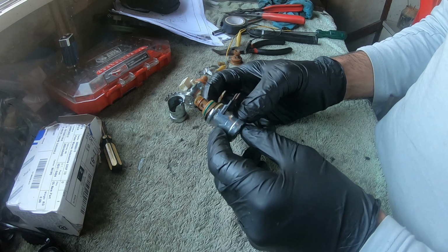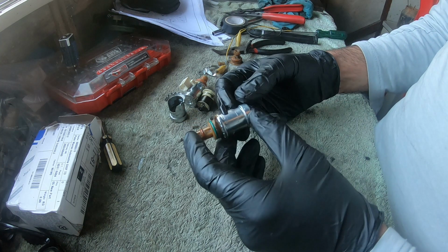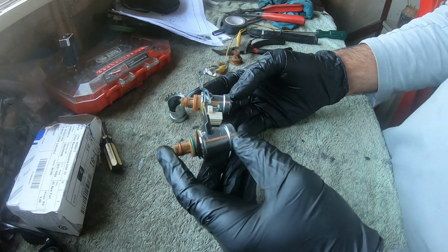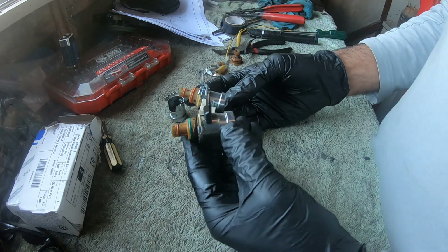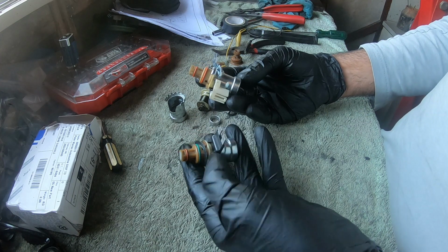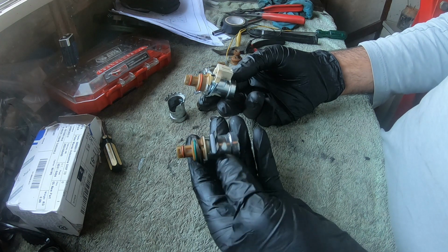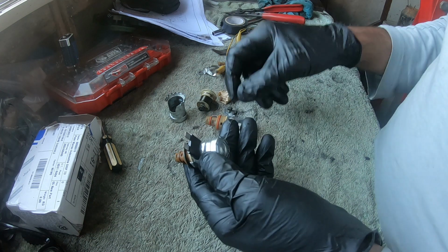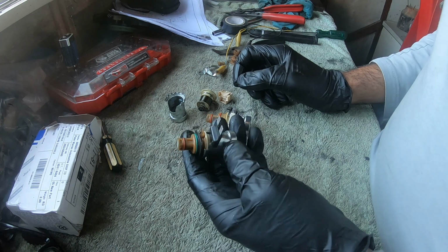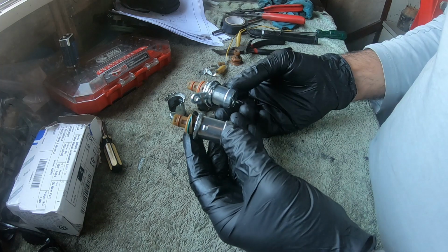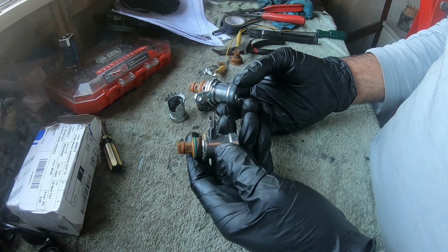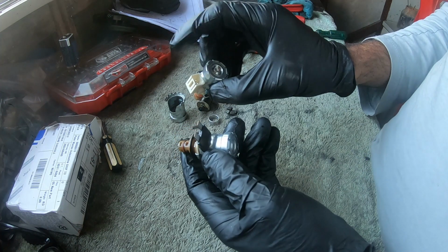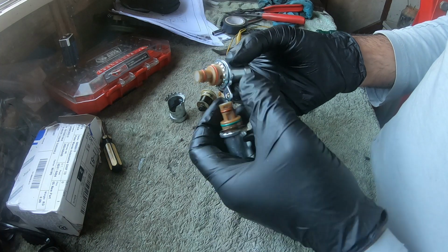In the meanwhile, I realized that this line pressure solenoid and this TCC solenoid are constructed extremely similarly. The electrical properties are the same, the size is the same, it's just that the shape is a bit different. You can have a look and see for yourself that it slightly looks different, but the rest of it is the same. Even the resistance for both of these is identical. I had a better look and realized that they are the same part. It's just that one of them is given these particular connector shapes and the other is given this connector shape, plus a hook on here.